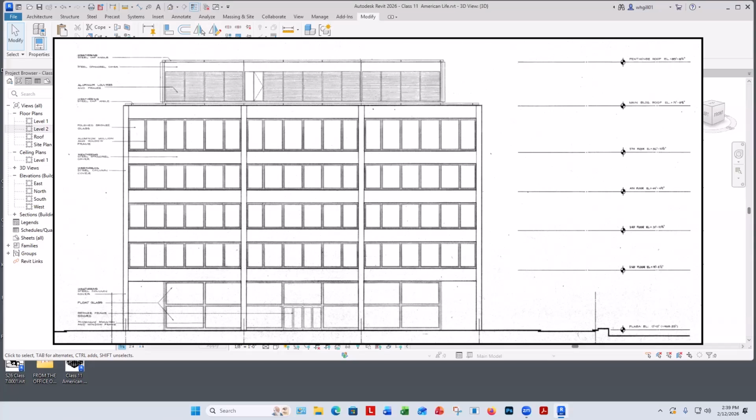So I'd like to measure from the plaza level up to the bottom of that first spandrel. So that's 12, 13, 14, 15, 10. Let's call it 15'10". What's the height of this then, this first spandrel, heavy line to heavy line? Start with putting your 0 where you want to start, like right here. Let's call it 4'2". Okay, 4'2". Somebody else. We get 8'4" for the glazing system, glass on frame. 4'2" and 8'4". Actually, and these are 12'6", so that all adds up perfectly.